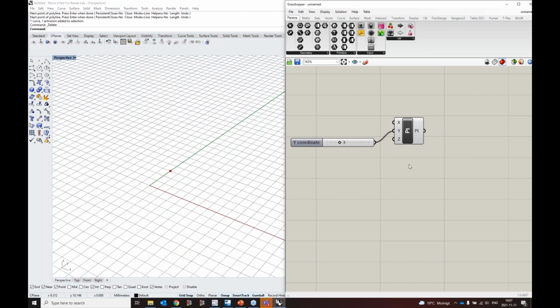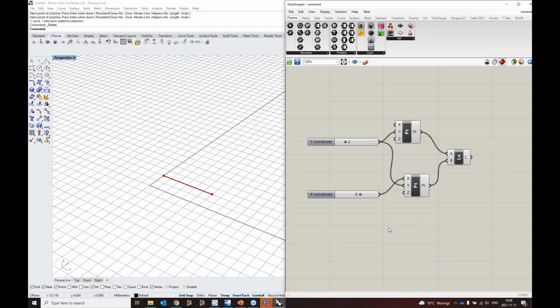And you can move it around. You could also have another point. Let's just do maybe this. And then we could create a line object between them. And if we change these, you see that the line also follows along. So that's the basic concept of parametric modeling, which you can do in Grasshopper through Rhino. And you saw that to find these components, I just double-clicked the canvas and I wrote the name of them. And I think that's a nice way, but you can also look through these different tabs and find the different components that are built in.